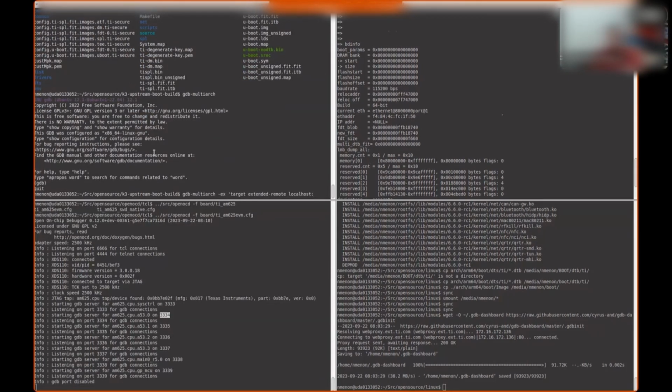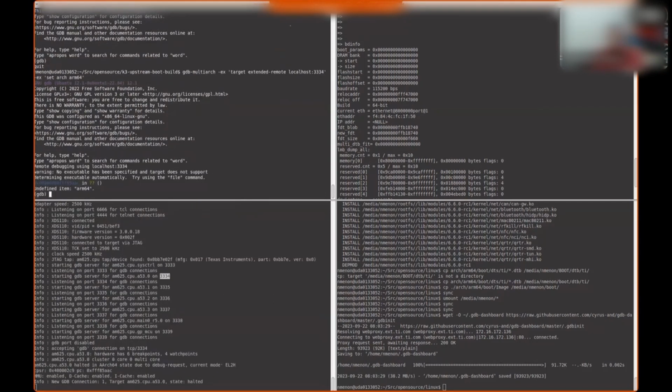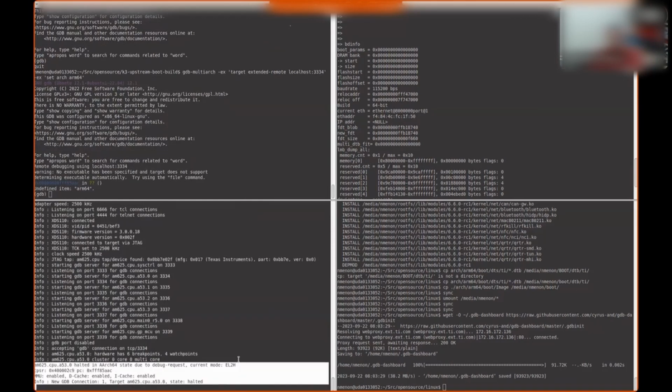I'm going to debug 334. And I'm going to set arch to aarch64. I'm going to debug in ARM64 mode. Boom. It has already attached. Notice at this stage, you see this message coming out of OpenOCD that says current state is EL2H and the state has been halted.